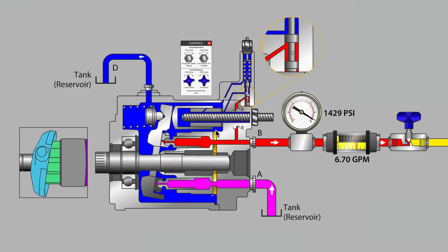So anytime the pressure increases inside the pump, as is happening for all of the pistons that are working against the outlet as they eject oil from the pump into the hydraulic system, all of those pistons are under fairly high pressure, the cylinder barrel as well. And so you're seeing little white arrows in a number of places in our animation.